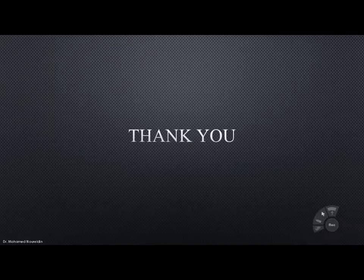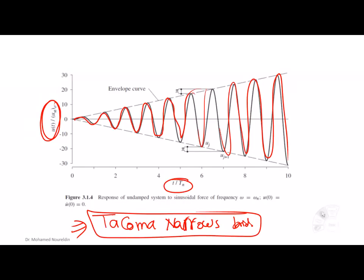If our system is a ductile system, whenever there is amplification in the motion, the ductile system is going to change its stiffness, and then it is going to change the T, which is going to change omega.